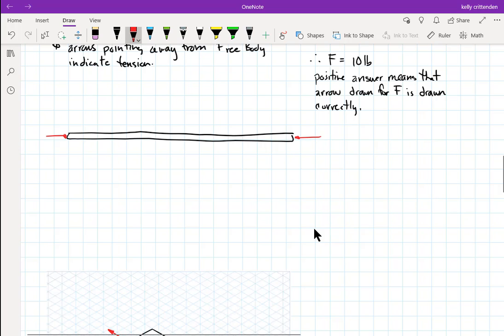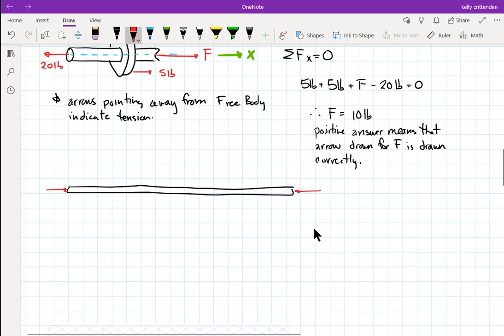So if you've ever taken like a yardstick or whatever, something long, or a dowel rod and pushed on it, then it probably didn't crumble under you pushing on it, but it bowed out. And so that's a different thing. Another reason to know tension from compression is because different failure modes occur under tension and compression. So it is important to get these signs correct, not just for the math to work out, but the actual failure mode might change when it's tension versus compression.